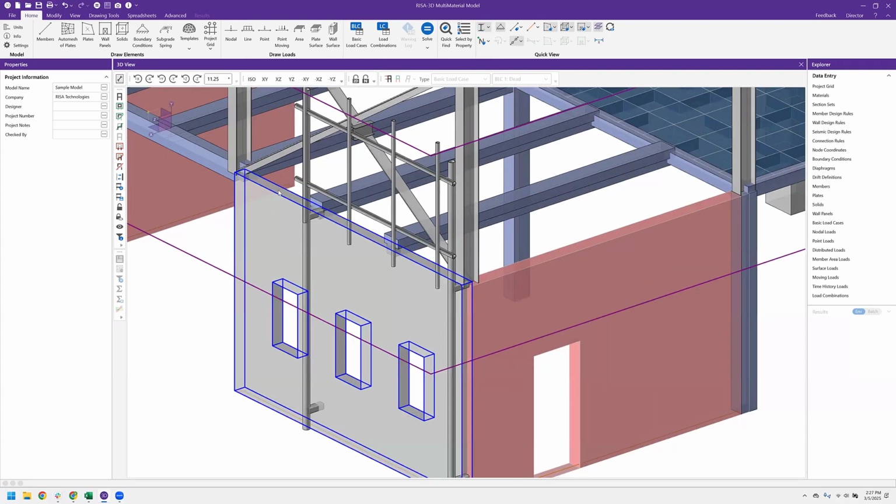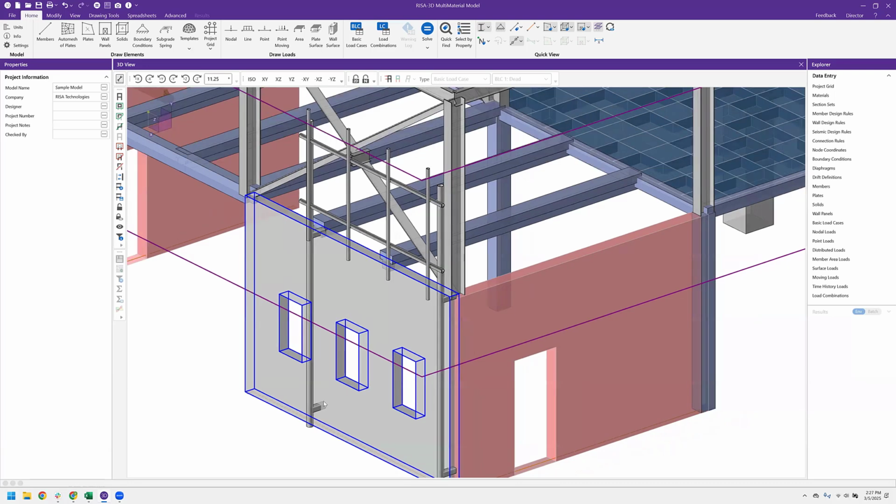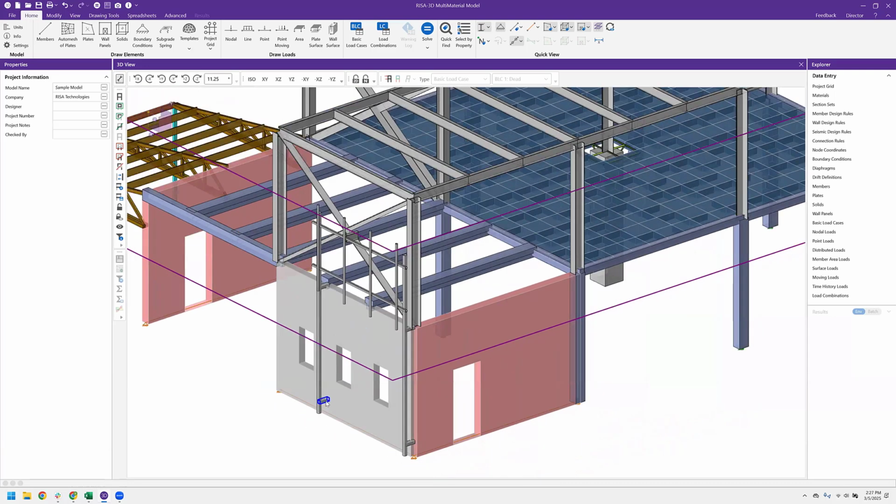And if I wanted to shift it down the concrete wall here because I had to, I could. But essentially now I've got this steel structure that is attached, or will be attached, to the wall because this wall will mesh. Then I can go ahead and apply loads and get the analysis as this antenna mount is impacting that concrete wall. And so again, this is really any type of component template that maybe you can think of.